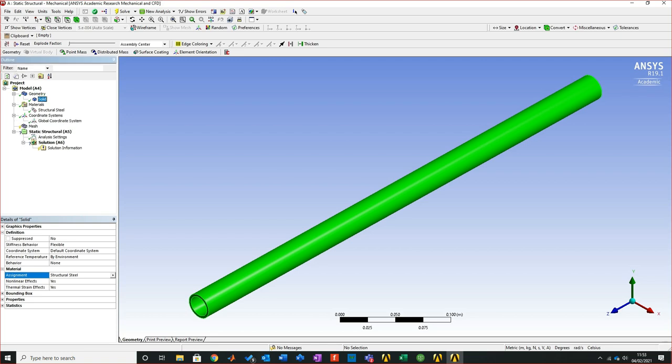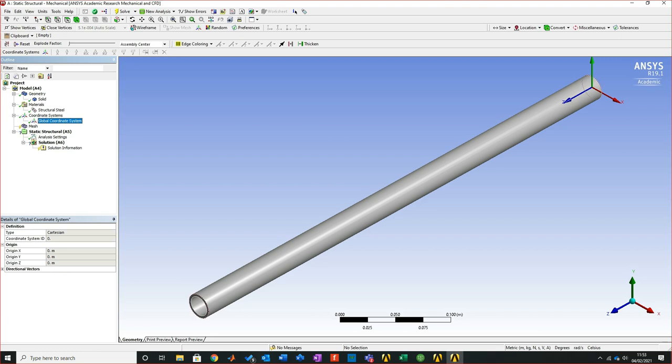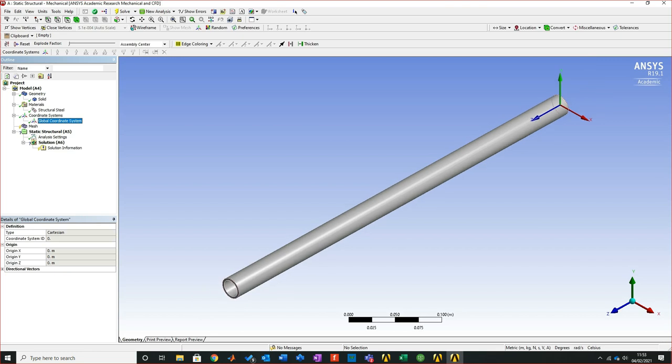So when we come down, we've got the global coordinate system. See how this is measured here? If you have something that you're trying to emulate a behavior, so for example, let's say you've got a linear actuator that is essentially used for landing gears, or any type of mechanical system, a large lifting system, but you want to keep that computational element low, want to keep it down. What you can actually do is add further ones in here, and you can say that global system is moving in this direction. And all it'll do is just concentrate on your geometry. It's just a sneaky way of keeping things minimalized when it comes to computational elements.